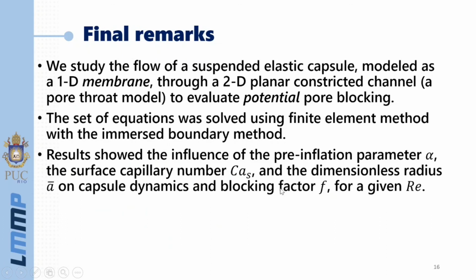Finally, we study the flow of a suspended elastic capsule modeled as a 1D membrane through a 2D planar constricted channel, a pore throat model, to evaluate potential pore blocking. The set of equations was solved using the finite element method with the immersed boundary method. Results show the influence of the pre-inflation parameter alpha, the surface capillary number, and the dimensionless radius on capsule dynamics and blocking factor F for a given Reynolds number.